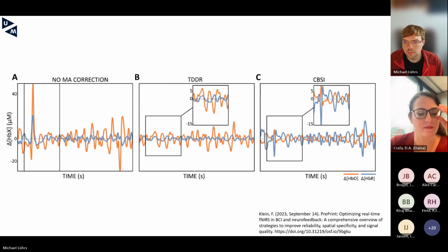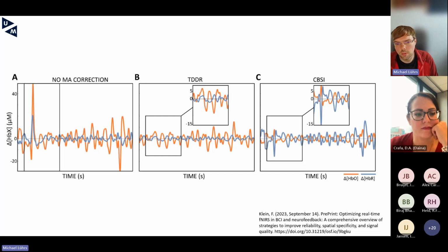But you need to be aware that this is only possible if, in the beginning, the signal was already somewhat anticorrelated, so that the motion artifact correction can work, because then it is able to find differences that were induced only by the motion. But if your signal was not anticorrelated from the beginning, this method has a hard time disentangling these artifacts.